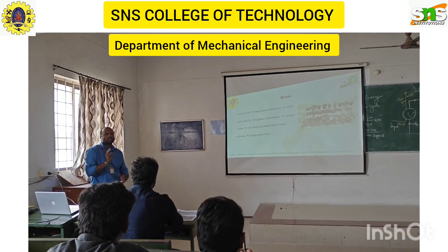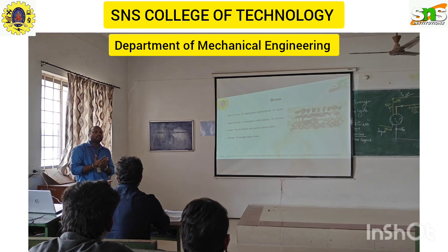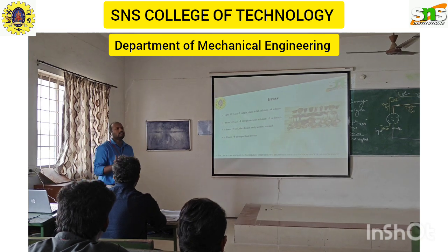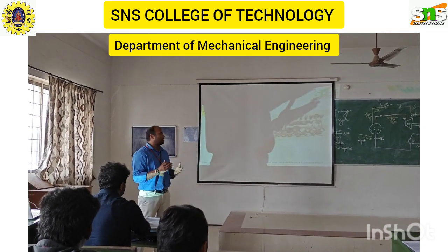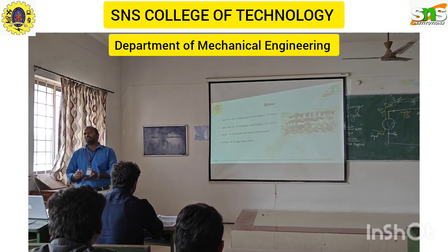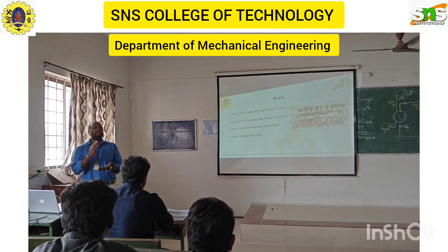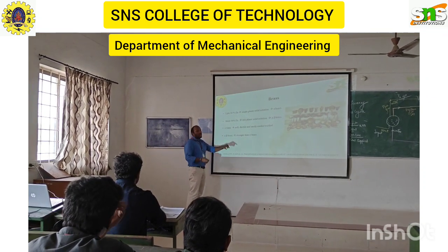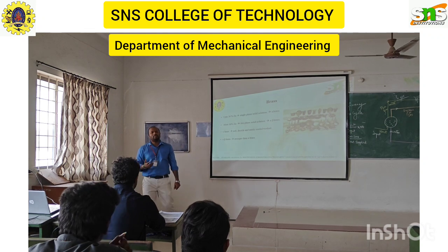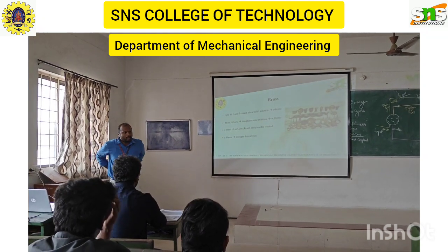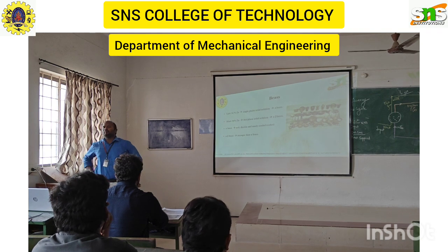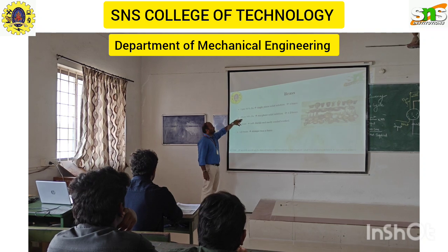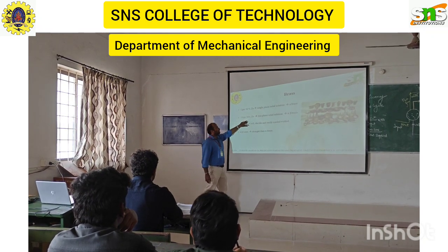First, brass is made up of copper as the major base material, and zinc as the additional material. Like steel, where we use iron and carbon as the two important materials, for brass we use copper and zinc as the base materials. If you add zinc up to 36%, it is known as alpha brass. Okay. As we see in the phase diagram, we say alpha and gamma, right? In the same way, up to 36% of zinc is alpha brass. If it is more than 36% of zinc, it is going to be alpha-beta brass, because we have two phases, right?